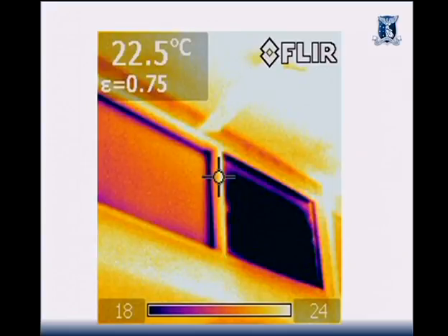Okay, this is another example of a thermal infrared, just showing this is still heat flow. What do you think is the difference between those two windows? This is my house now. Damn you, yes, it is. So the one that's double glazed, it looks like it's got a blind down, or it looks like it's got some sort of insulating coating, and it's exactly what's going on. The other one's, of course, just leaking heat out.